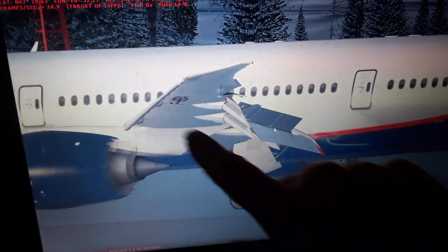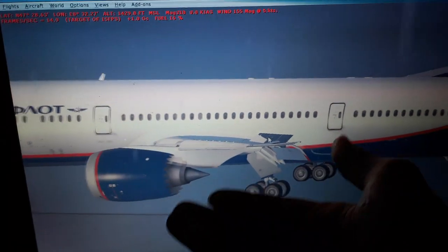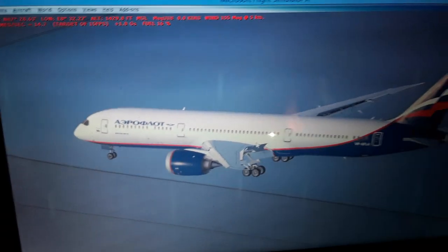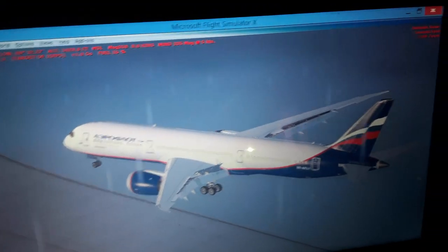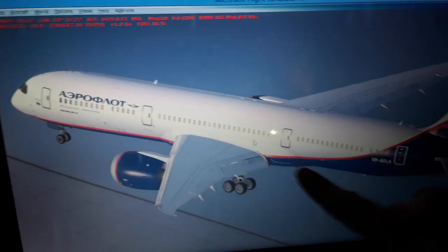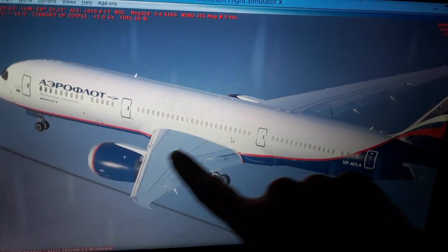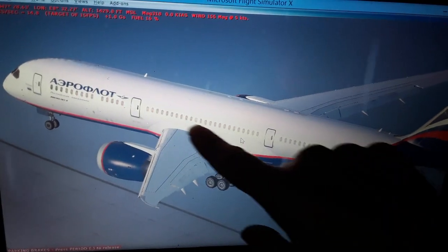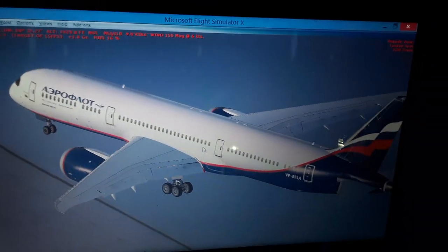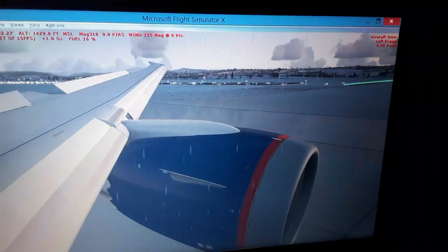So we have lower airspeed of the airflow using the Bernoulli theory of fluids, so we have higher pressure, which pushes the aircraft weight and wings up into the air as we fly. We have higher pressure below the wings. Also you can see the top surface of the wings is more curved, so as we fly we're going to have higher speed of airflow above the wings, which creates lower pressure, which sucks the aircraft weight and wings up into the air. So this is the explanation for flying, the aerodynamics.